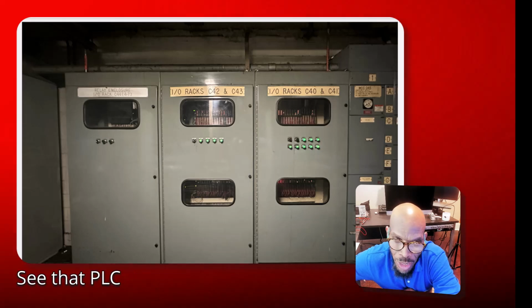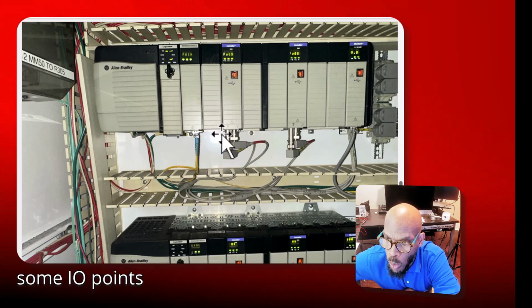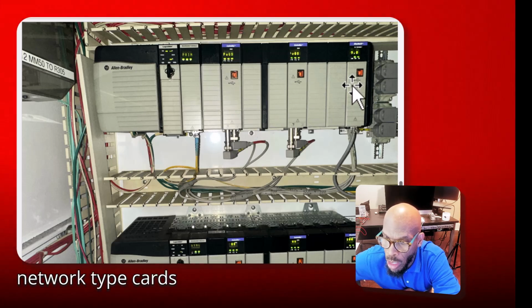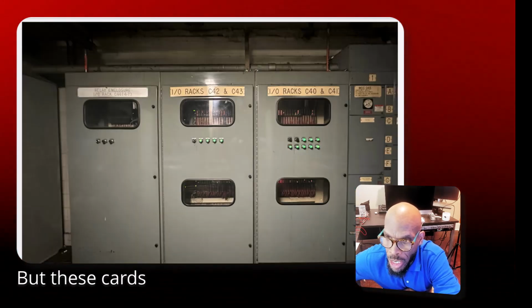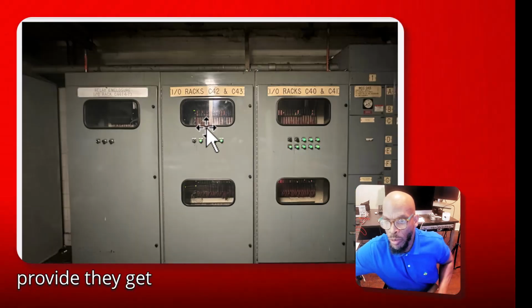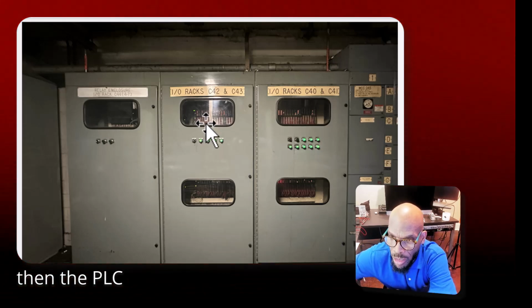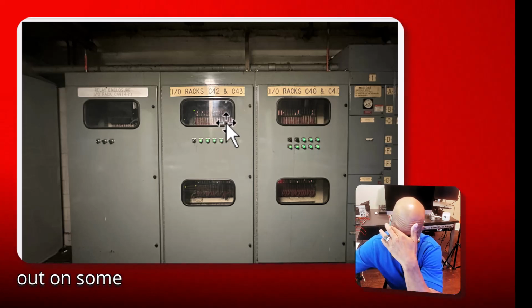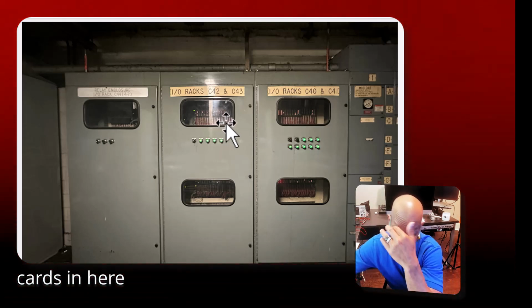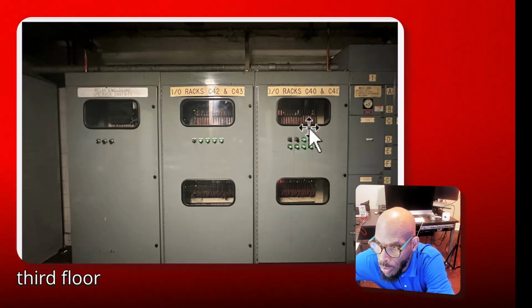See that PLC that's right here? It's got to have some I/O points. These are just network type cards right here, so it's hooked up on the network. These cards get information from sensors, then the PLC operates, and then it sends signals out on some of these cards, on the output cards in here. So remember, this is on the 3rd floor.